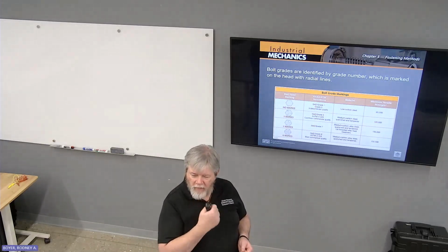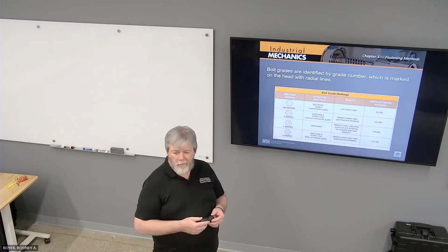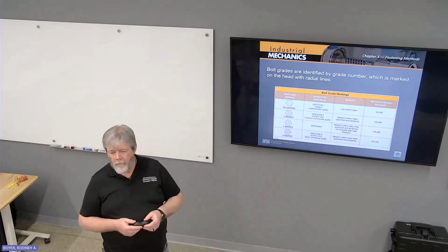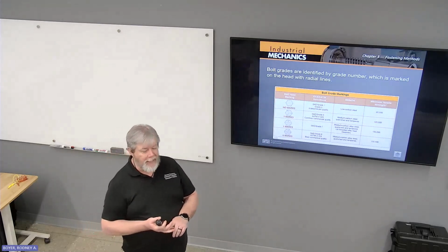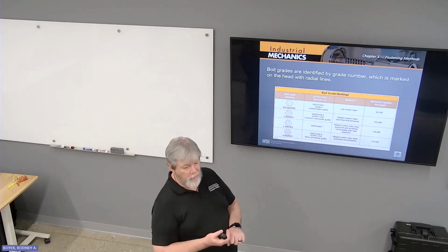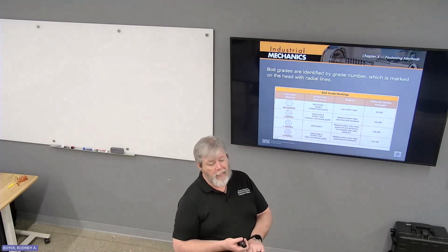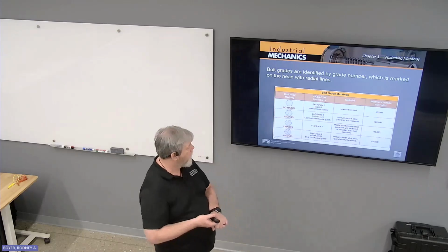You remember yield strength? That comes into play there. There's also stretch right there, and elastic versus plastic deformation. Elastic deformation, it will return to its original shape whenever you relieve the stress. Plastic deformation, you have exceeded the yield strength and it will never return to its original shape. Basically what that means.